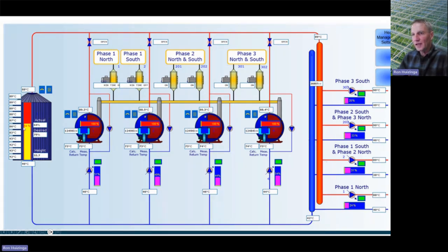And we're only looking at these 2 sensors when the tank is less than 50% full of heat. You can see that the top sensors are 89, 88, so they're all pretty close, but then you start getting some mixed temperatures here, a couple of mixed temperature sensors. So we always want to have the tank at least 50% empty before we start looking at this. Otherwise, we start looking at sensors that have a little bit of mixing of water.